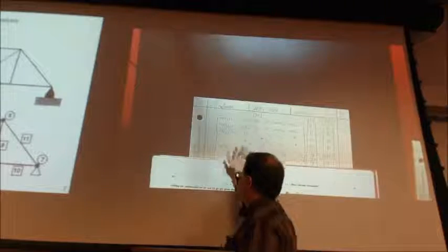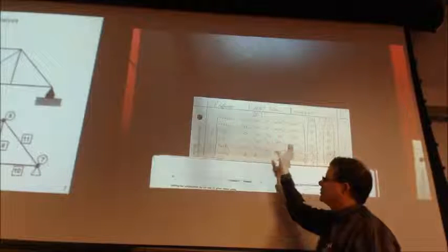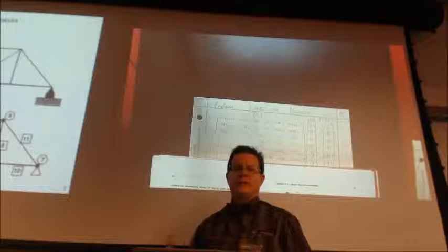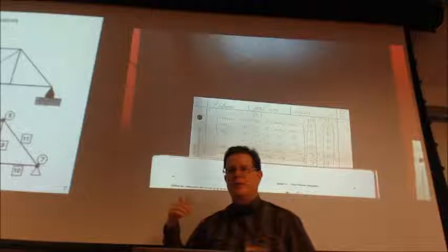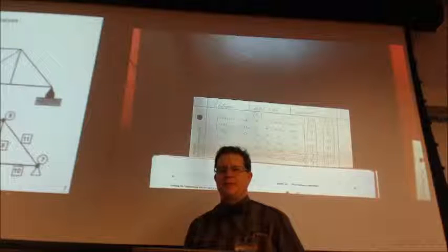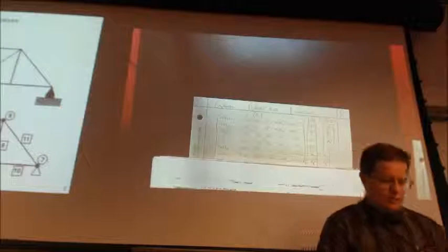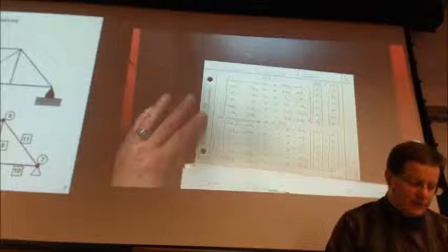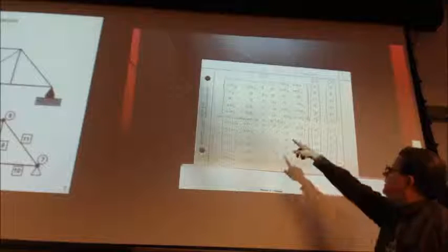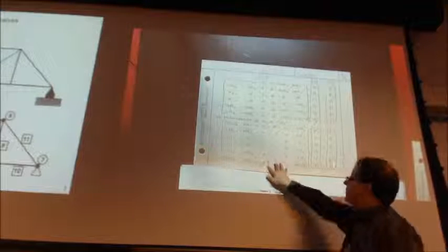So what's the first thing we do when we get to this point and we have our structure, our matrix all set up? We're going to start considering the load or the boundary conditions, right? So we can start canceling stuff out and reducing. So we know that we have no displacements at U2, V2, and U3. So those all go to 0.